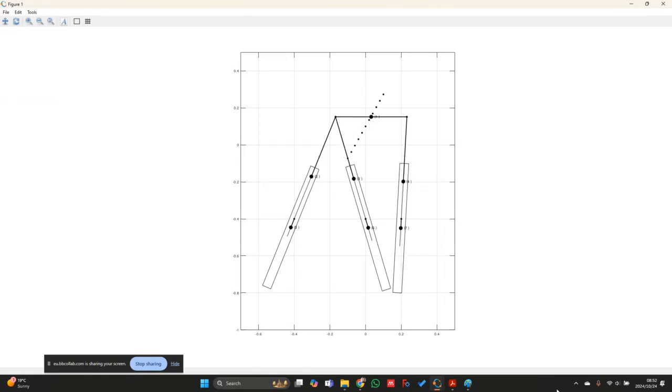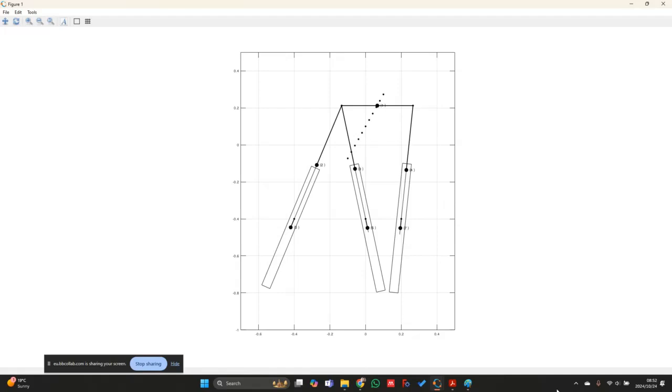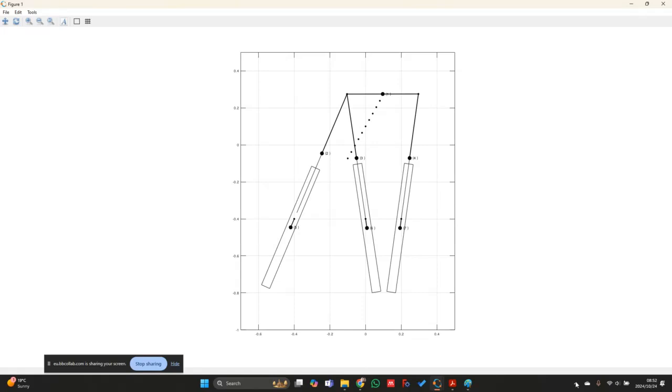This is not the newest laptop that I have, but I think the computers that you will have available will run these simulations fairly quickly. So you don't have to worry about waiting too long, as long as you just use a fairly coarse reporting time step. And then once you're happy with the actual animation, then you can go and make the reporting time step a bit finer to either generate graphs or to just simulate according to the question. Like in this case, we now use a 0.4 second time step.